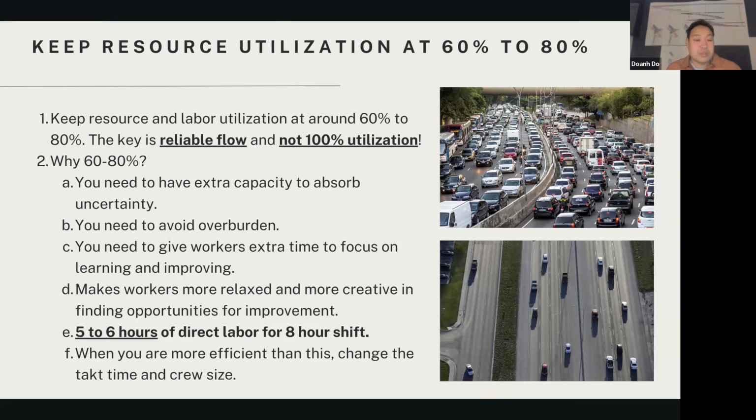Typically what we do is we start with a TAKT, let's say a 3-day TAKT. As the team gets better, we may transition them into a 2-day TAKT and then a 1-day TAKT. So that's a natural way of absorbing all the positive gains in efficiencies, because they're working on the same zones over and over.